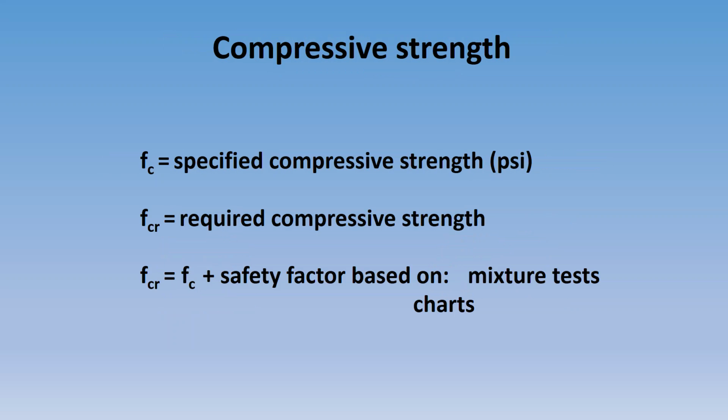So compressive strength is, again, what most people attribute to concrete. It's how much force that concrete can withstand before it fails. And we measure it in PSI, pounds per square inch, right? It's how many pounds every surface inch of that concrete can withstand without failing.